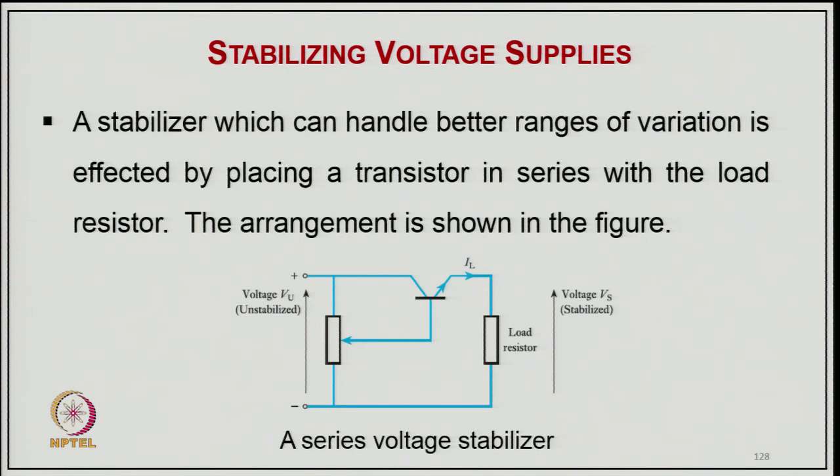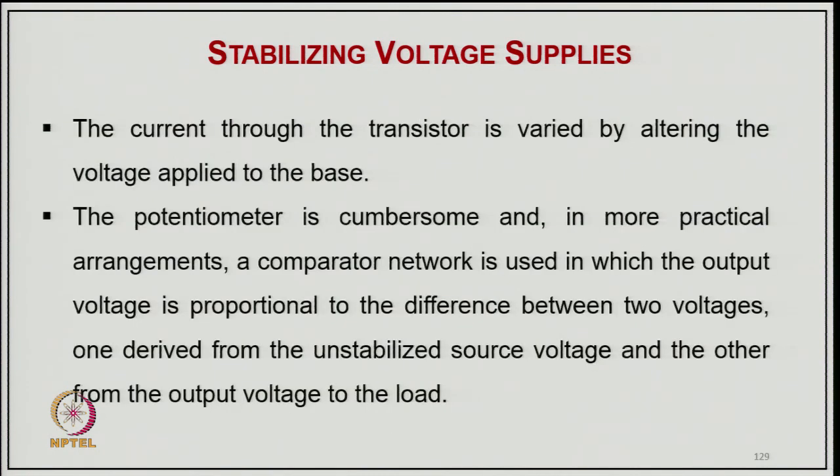Most of the regulated power supplies you might have seen in the laboratory work this way. So, that is the basic concept I wanted to discuss, the transistor as a stabilizer used in stabilizing circuits. So, we say the transistor stabilizing voltage supply is for high power, because a Zener cannot work for that much power.